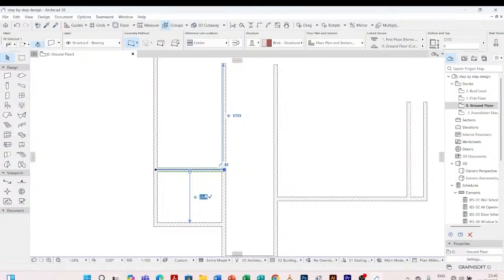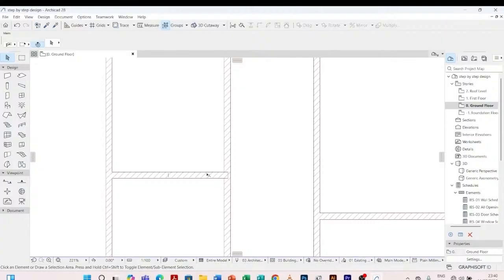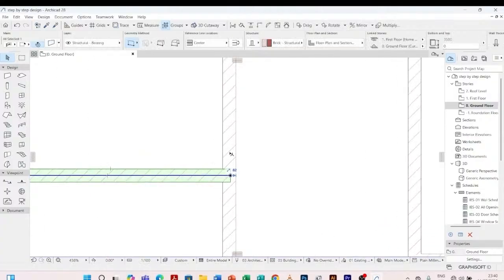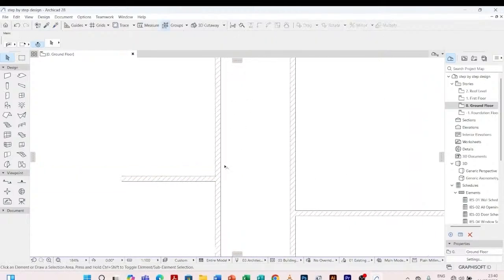It is just a study room. Click on enter. I activate it. To avoid this intersection, make sure they join at the middle. So you can click on this wall, you come and adjust. I'll pick the middle of this wall. So that's what will happen.